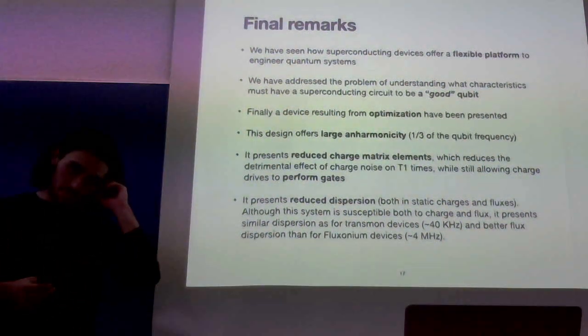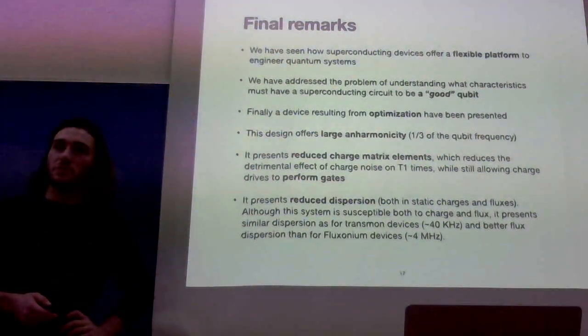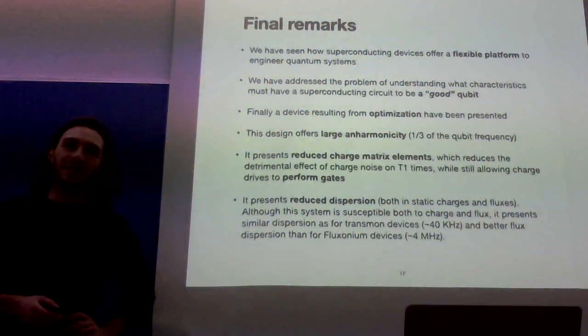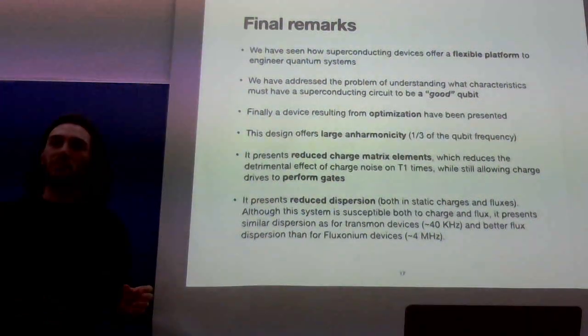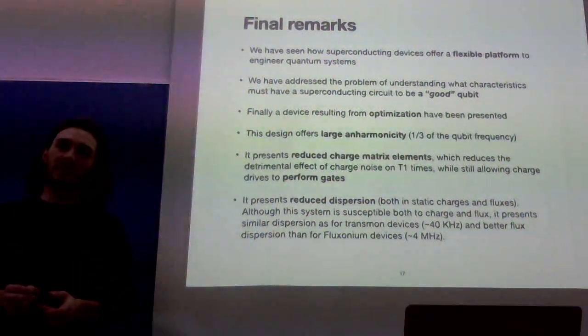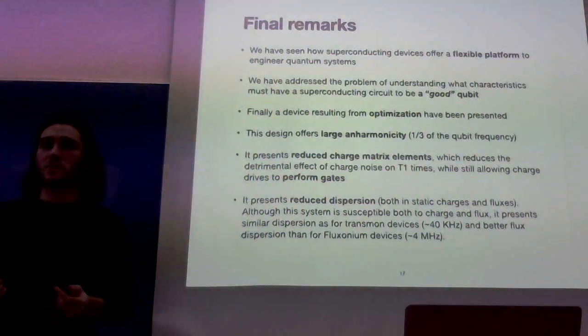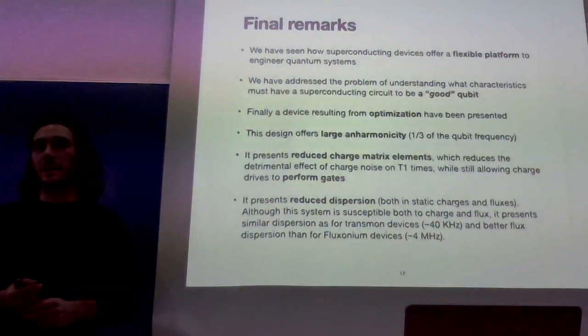Yeah, I mean, it's a combination of both, because first we have to find realistic values for the physical parameters. People tell you, we can make from this to this, but in fact, if you have a chip size of 800 micrometers times 800 micrometers, and you have two islands, of course, you can reach a capacitance of like 70 femtofarads.